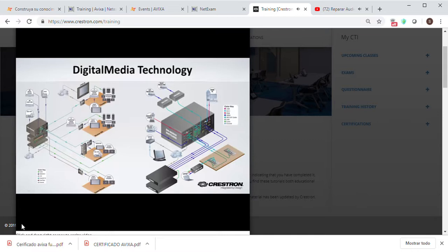Crestron Digital Media offers an extensive selection of transmitters, wall plates, HD to SDI, 3G to SDI, and DSP input-output cards. Digital Media also offers a variety of receivers with a built-in power amplifier and scaler, fiber solutions, and other integrated products. Crestron Digital Media distributes uncompressed digital audio and video signals over a choice of shielded twisted pair copper wire or fiber optic cable.